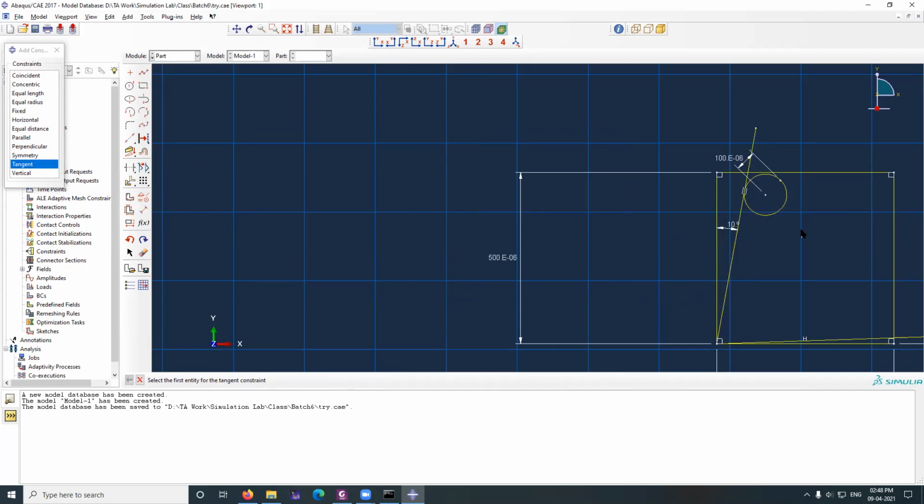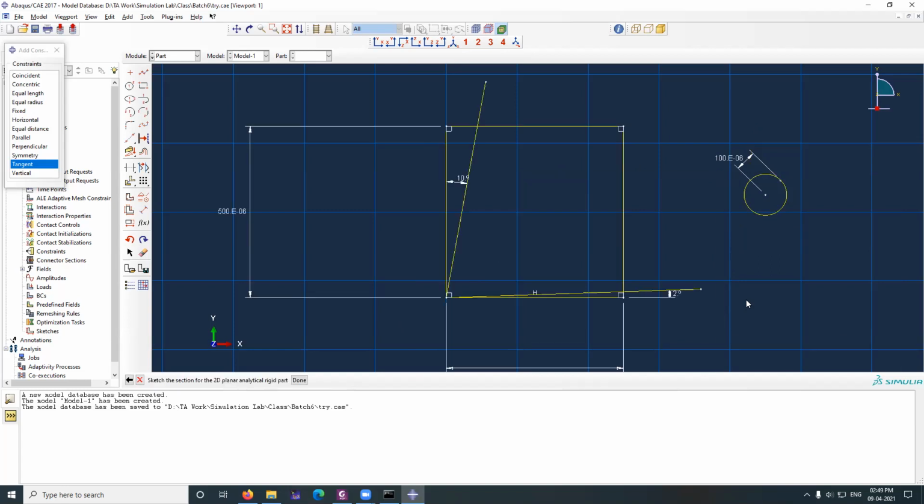Okay, this and this. If you click it, you can see this particular one moved according to the circle. I don't want that to happen. I want this circle to move to this place. So let me do Control Z. You can fix these lines, so that this will move here. So let me fix it. Fix this line and shift this line. Okay. Now these lines are fixed.